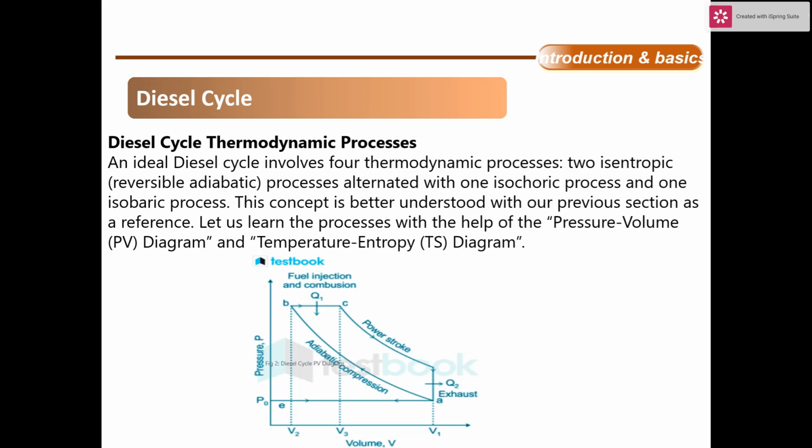Here, the suction stroke. The first procedure that introduces air into the cylinder is the suction process. The piston is at the top dead center, TDC, position, and the piston moves from TDC to BDC when air is introduced. The inlet valve is open during the suction operation, and the exhaust valve is closed.